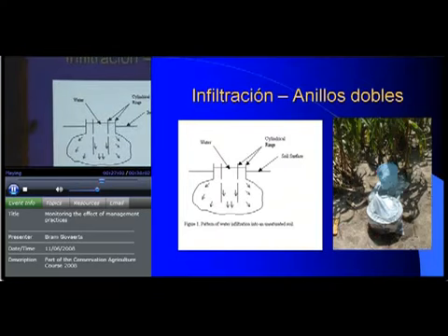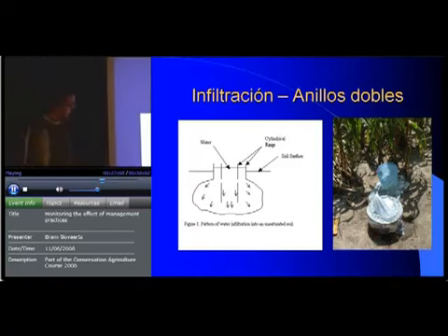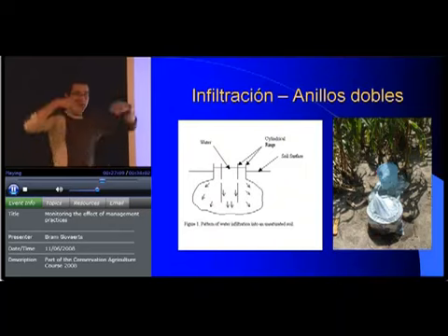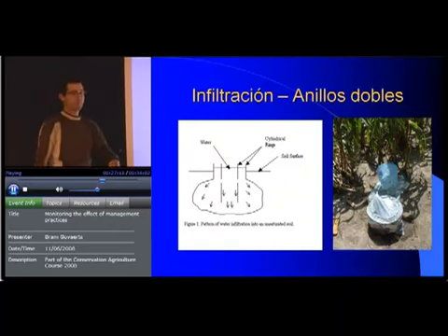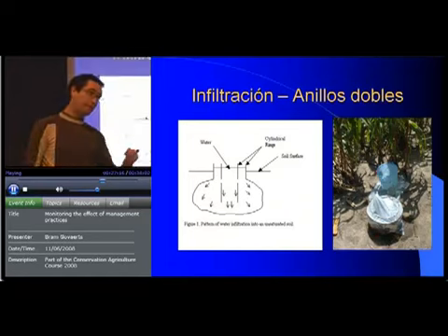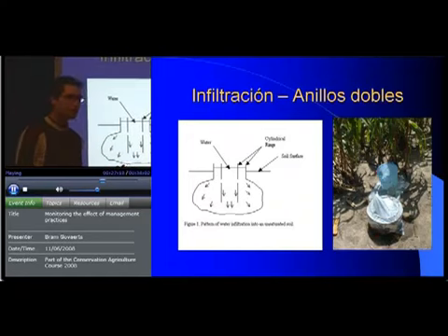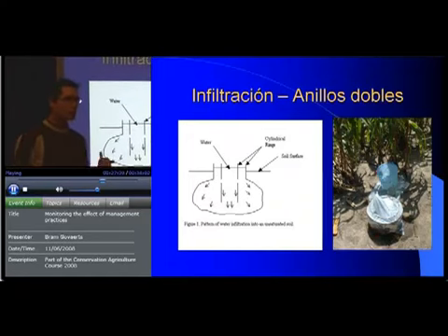That's why you do it with a double ring. So that you have the saturated infiltration rate downwards. That's okay. But it's maybe a value that's difficult to measure, and second, for zero till, it's not always really reflecting what we want, right?